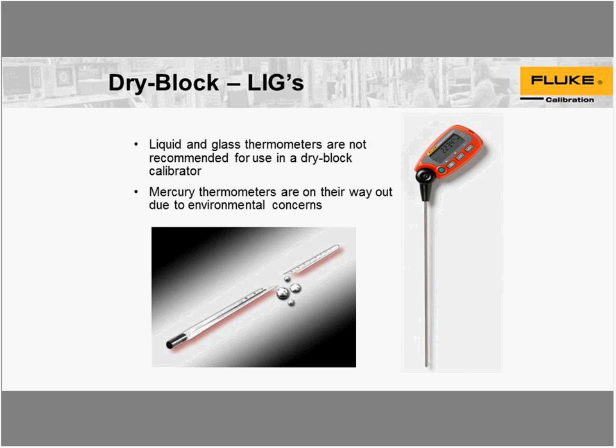Another common thing that comes up with drywells is people will ask, well, can I calibrate my liquid-in-glass thermometers in them? I have some people do it. It is not recommended. The reason is that mercury thermometers have a bulb at the end that is the point of contact, and that bulb usually varies in shape versus the stem. So if you get a hole large enough to accommodate the stem, your bulb usually has a nice air gap around it, which results in low readings.